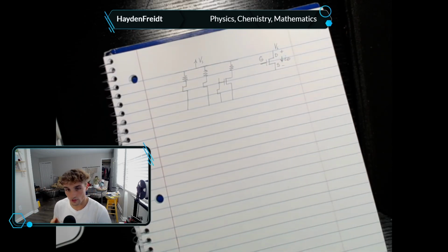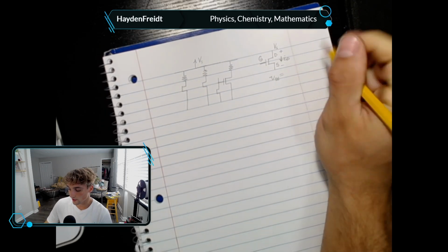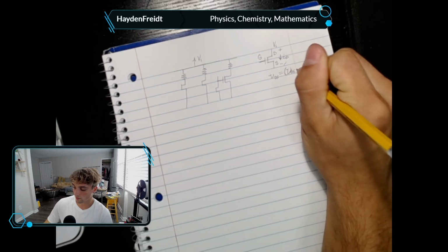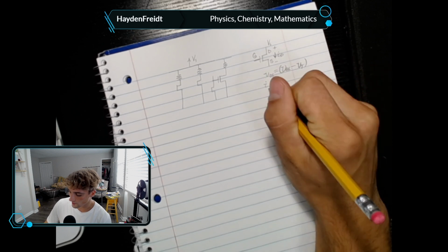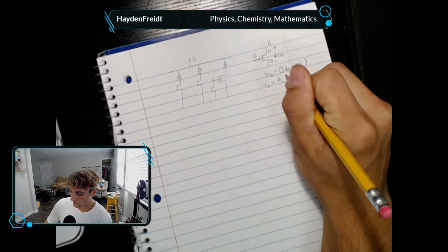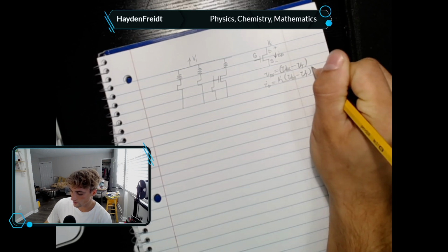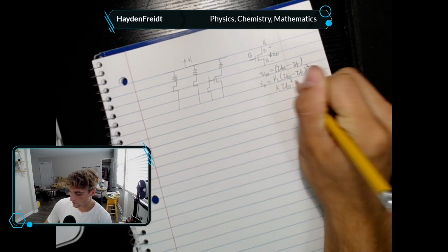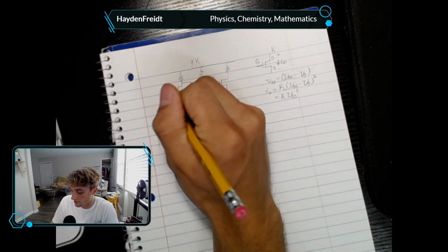We would model it as a voltage controlled current source. The voltage across the drain to source equals the voltage across the gate to source minus the voltage threshold. We want a relationship for the current, so we would have ID equals K, this is variable K, multiplied by this difference, VGS minus VT, squared. So you could also write this as K times VDS squared. Looks much better. That's not really beautiful, ain't gonna lie, but it's looking okay.